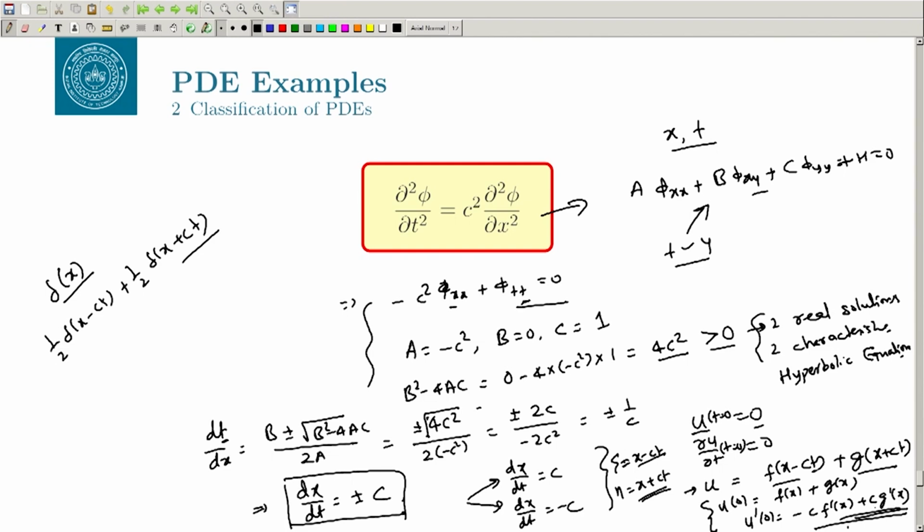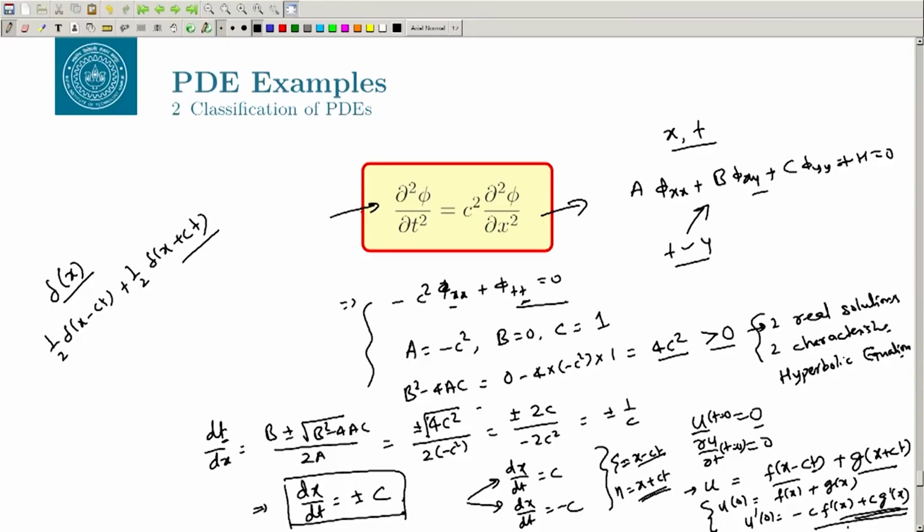So, the hyperbolic system is a very interesting system, and this will be very useful when you go to high Mach number flows. The Navier-Stokes equation displays different behavior depending on the regime. Let us say if it is a very low Reynolds number and low Mach number flow, then it is more like an elliptic system, and your viscous term dominates over the other terms. On the other hand, if it is a very high Mach number flow, then the behavior of the system is hyperbolic-like, where the advection term dominates. This looks like the advection equation that we have discussed.